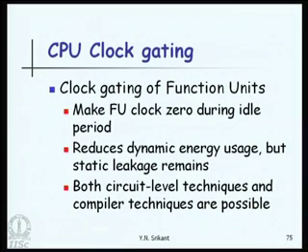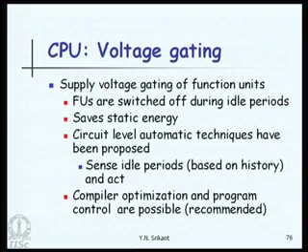Both circuit level and compiler level techniques are possible in this case for gating the CPU clock. We will see that a little later. So, supply voltage gating is another possibility for function units. What we saw before was supply voltage scaling for the whole CPU. Now, we are looking at the supply voltage gating of function units.